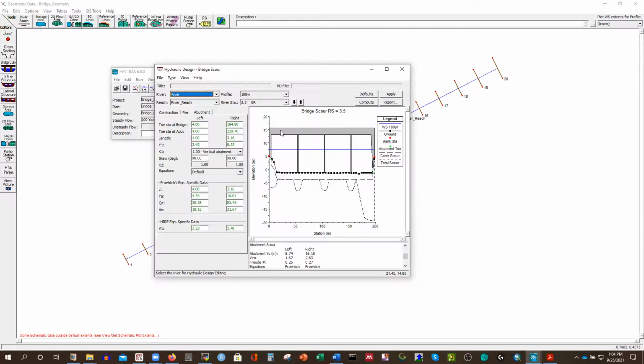If the flow rate, meaning the discharge, and the velocity and the depth of water are all constant with respect to time, then we call it steady flow. Otherwise, if these hydraulic parameters change with respect to time, then we call it unsteady flow.